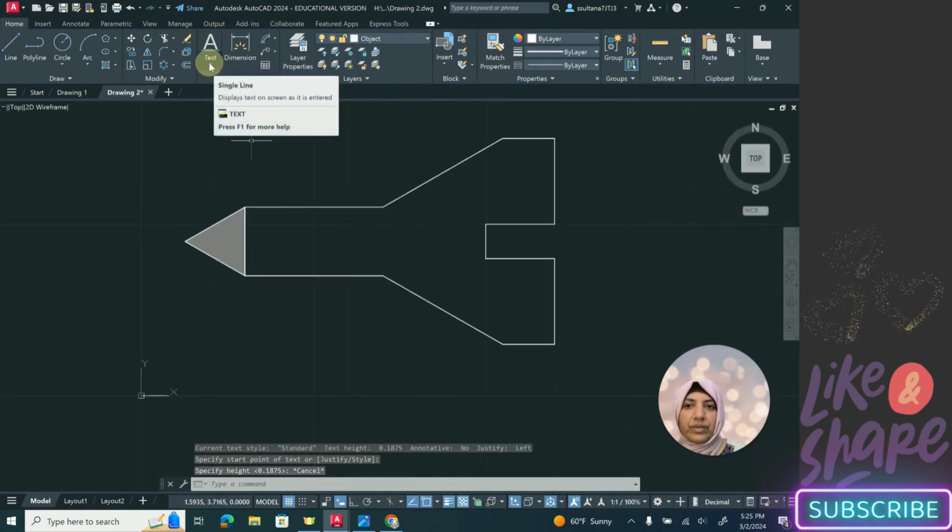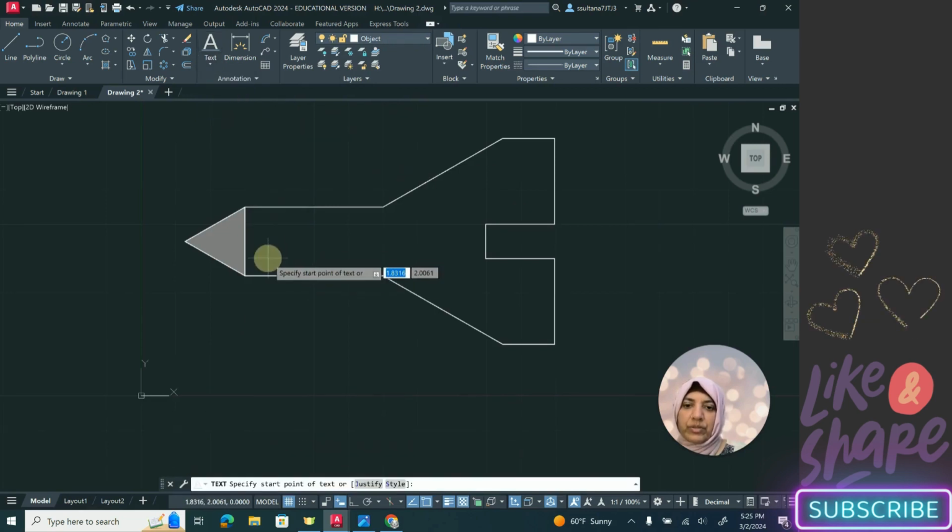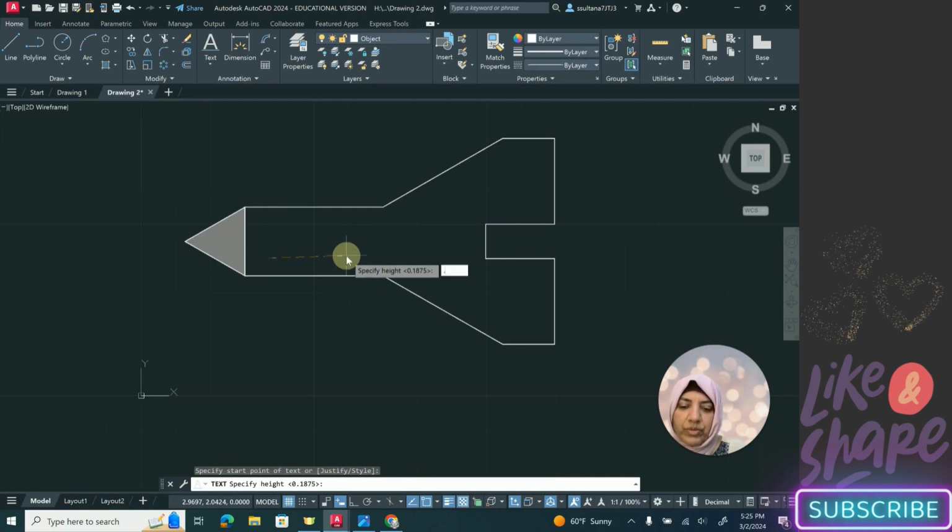Okay, now we are going to add the text. Single line, specify a start point of text. And now specify height of the text. And I'm going to give 0.25, angle 0.